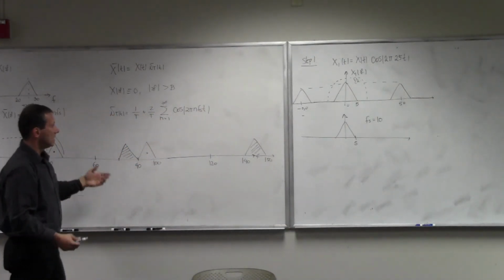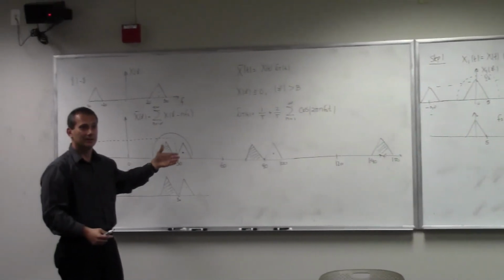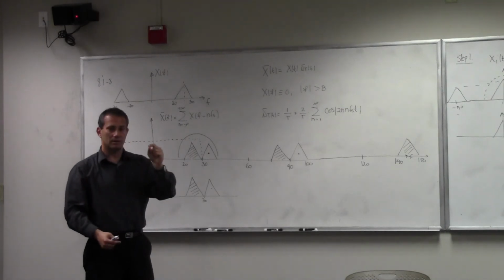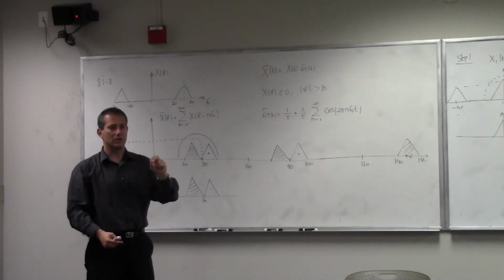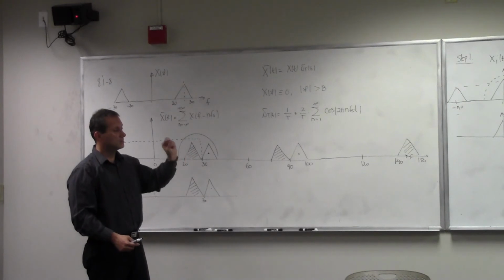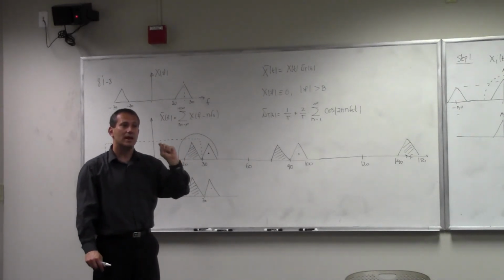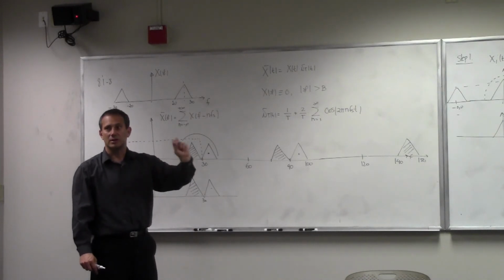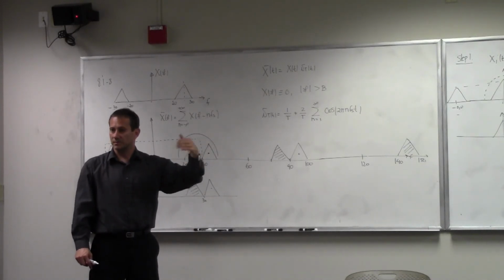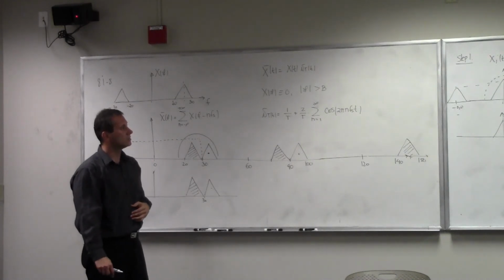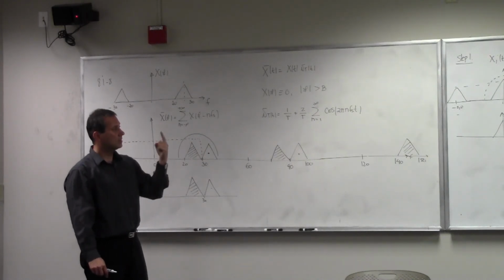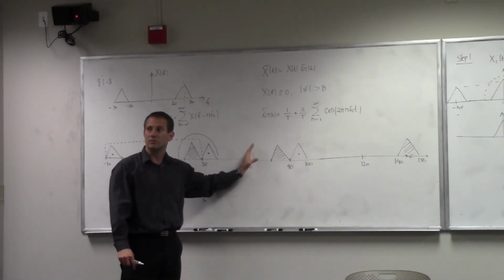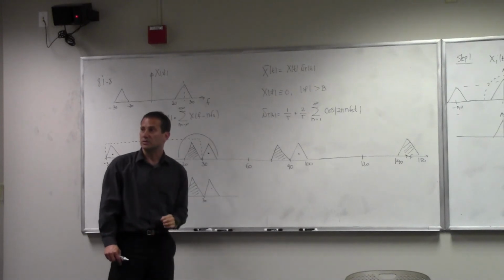So this is stuff that we do, right? In this kind of situation, what is really the only true thing theoretically here is that derivation that we had. What happens when you sample? You're performing a periodic extension of the signal in the frequency domain. That's the number one understanding. And the second understanding is, of course, the modulation property of the Fourier transform that allows you to shift the signal back.